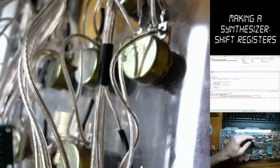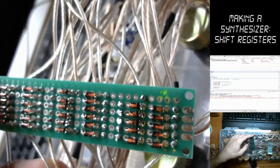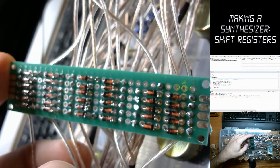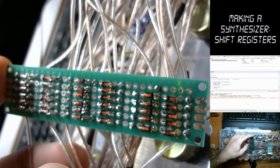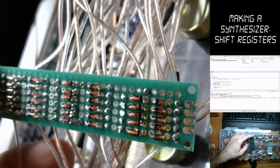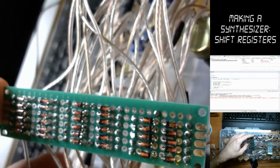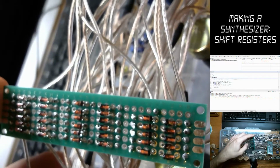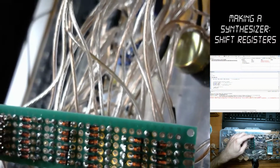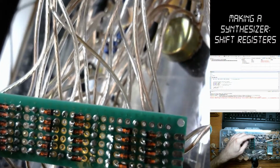inputs here. Then it gets passed through this bank of diodes, and that way if you press a couple buttons on different parts of the matrix, you don't get a ghosting effect, which is when if you push button 1 and button 8, button 5 may appear to be pushed, but it's actually not really pushed. It's just an effect where voltage is being rerouted through wires. So you put these diodes so they only go one way.